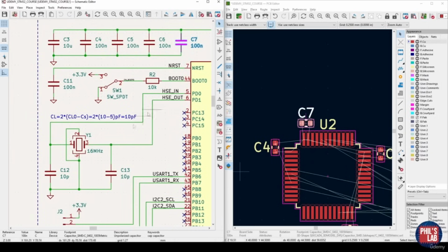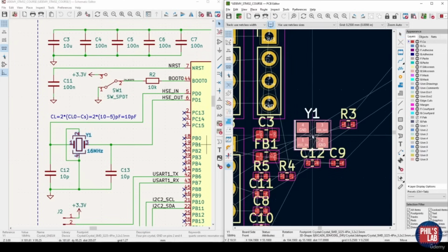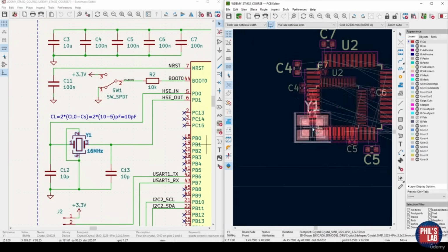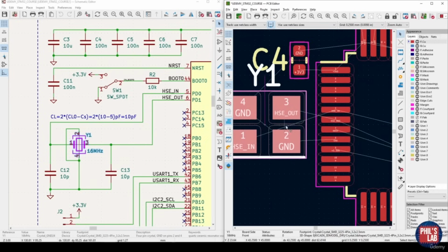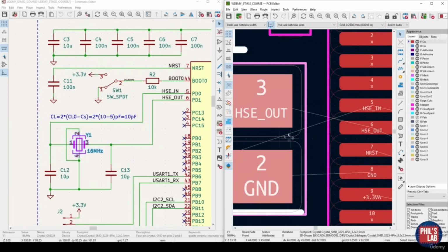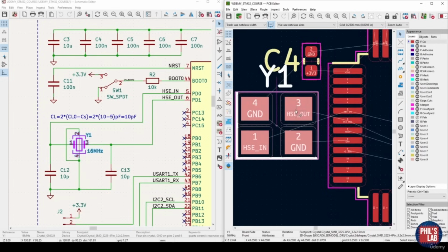What's important to me is this crystal oscillator section. So let's do that next. I can click on my crystal, press M to move, and just move over like so. And you can see with these rat's nests, what these lines are called, these very hard to see lines, these will tell you, okay, these are components and connections that aren't routed yet but need to be routed. This is a very straightforward way to see where components need to go.